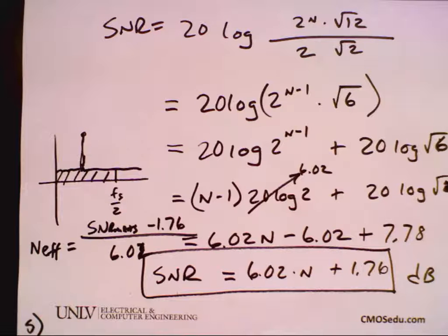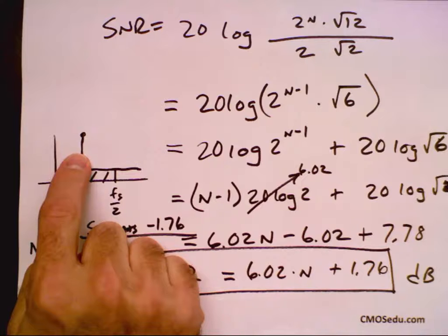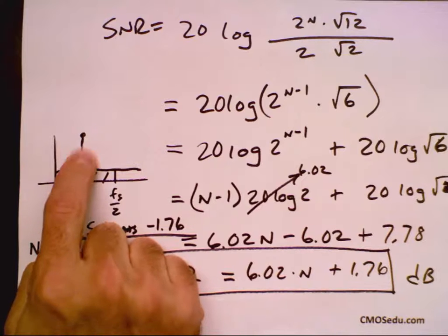My guess is in that case they're putting in lots of sine waves and looking at the difference between the measured point and the ideal point, and that difference is an error. Then you take that error and do it over many cycles and get an RMS value for the noise. Then it automatically removes the tone, so it's trivial to calculate the power of the tone.